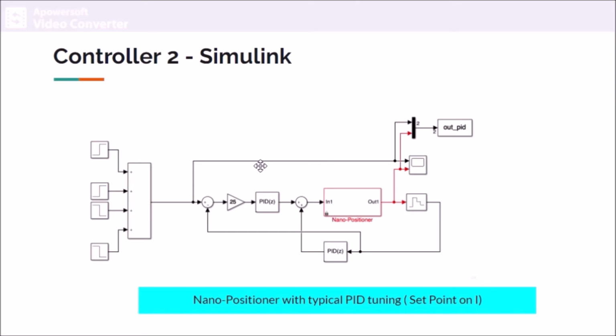We're going to explain later why we chose 25 as our gain value. As I mentioned earlier, we put the integral action here because we tried to make the entire PID block fit with the error, but we didn't achieve the required results, so we chose to separate it. Since the integral action only acts on the error, we fed it with the error, and the derivative acts only on the process variable, so we fed it with the output of the system.